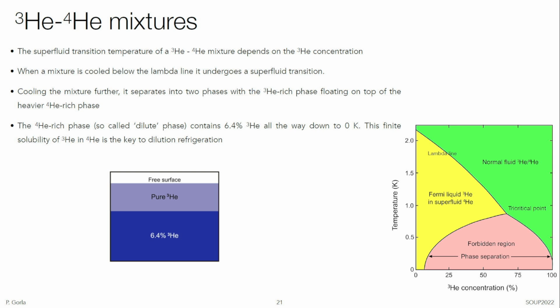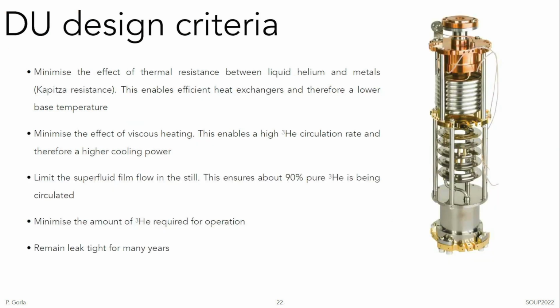This action of diluting is an energy consuming operation, and so the dilution is what eats the heat to bring you to the millikelvin temperature. Thanks to this process, thanks to the dilution, you are able to cool, nowadays, even large masses to extremely low temperature. Of course, the dilution unit design requires a lot of know-how.